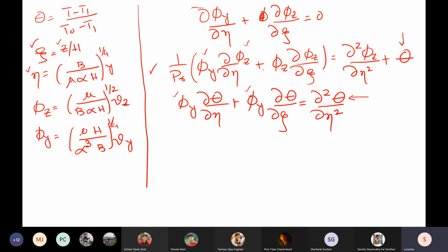So in terms of velocity, they are always coupled, but in natural convection, due to the presence of temperature also, there is a both-way coupling. The left-hand side of the equation of motion refers to convective transport of energy. The right-hand side has a diffusive or conduction term and the buoyancy-driven flow.